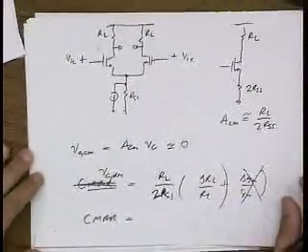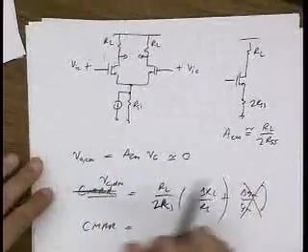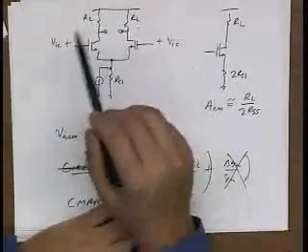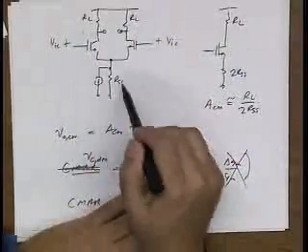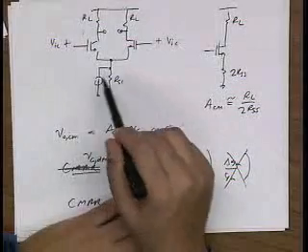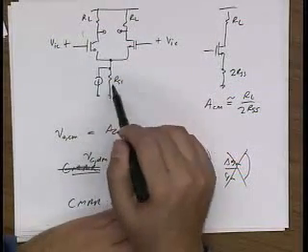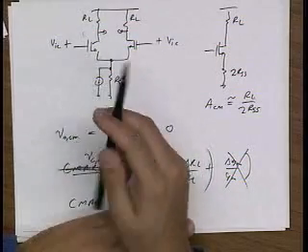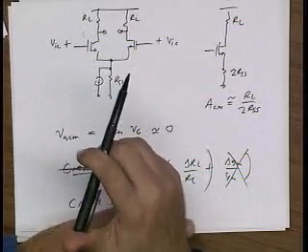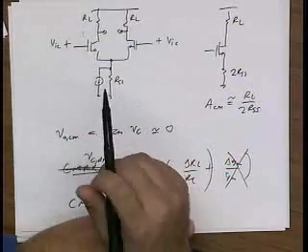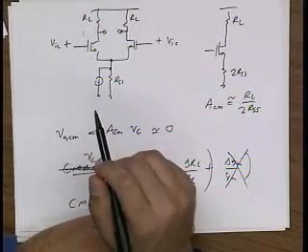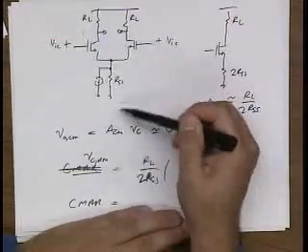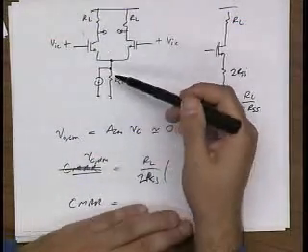All right, so let's keep on this topic a little bit. So what if I'm now using relatively small RLs, let's say a kilo ohm, and I really go crazy, I say I have lots of headroom, and I really want to improve my common mode rejection ratio, so I'm going to do a triple cascode current source here. Do you think I'm going to see that improvement? In other words, does this completely kill the common mode gain of the signal?